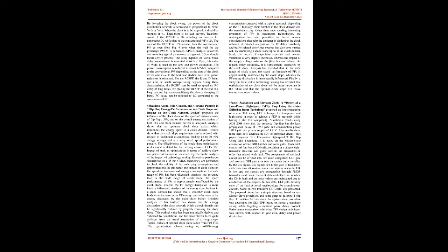Other than understanding interesting properties of FFs in nanometer technologies, the investigation has also permitted to derive several considerations that help the designer in designing the clock network. A detailed analysis on the FF delay variability and buffer-related skew/jitter sources has also been carried out. By employing a smoother clock slope at the clock domain level, the impact of capacitive crosstalk and process variations is very slightly increased, whereas the impact of the supply voltage noise on the jitter is even reduced. As regards delay variability, it is substantially unaffected by the clock slope.